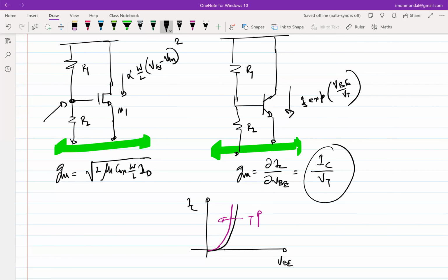So what is the solution? The issue is the current is not limited. The current keeps on increasing, right? Because you have biased it with constant VBE, and since you have biased it with constant VBE, you have no control on whether the current through the device is limited or not. Okay. So what is the solution?